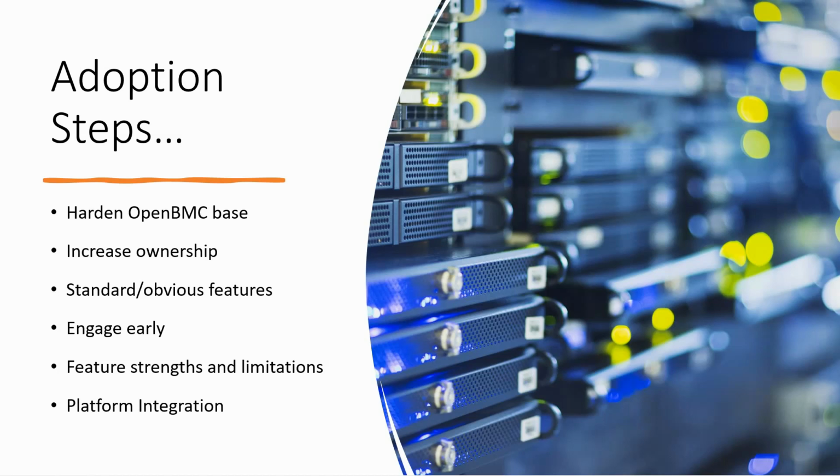And be aware that OpenBMC is not built with power on in mind. So it requires you to develop bare metal features that will help you to bootstrap your platform. This becomes very key, because some of the platform builders who have been doing it, or people who migrated from different areas to OpenBMC, may think that some of these things are a given, or that they have been there all along in eternity. BMC used to come after power on, and now it needs to go from power on back to BMC in order to retrofit it.